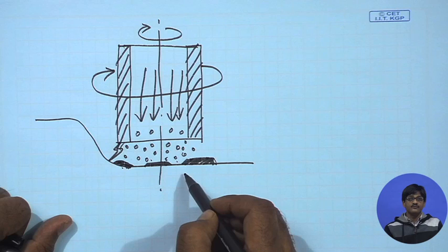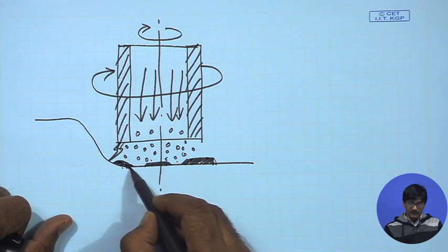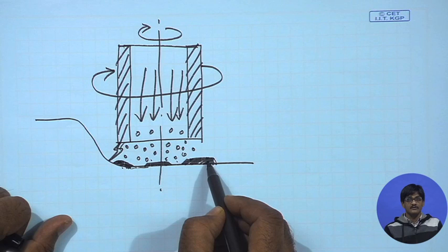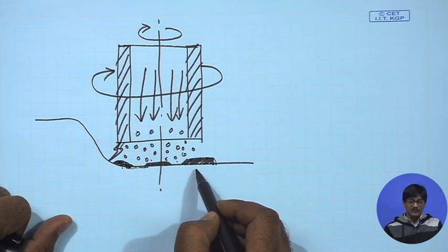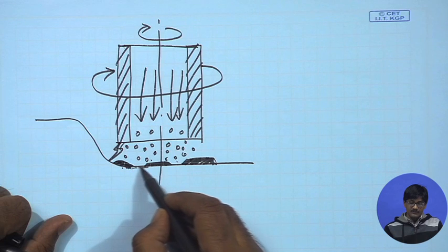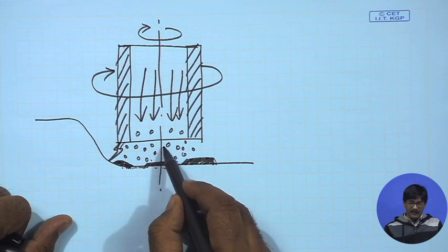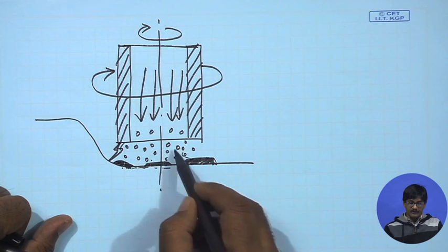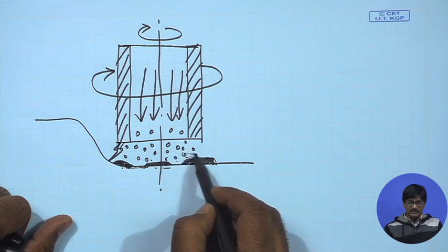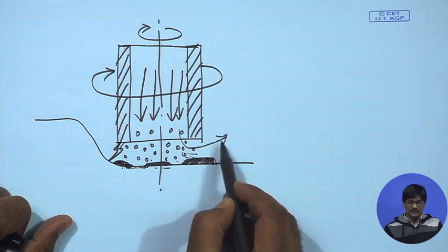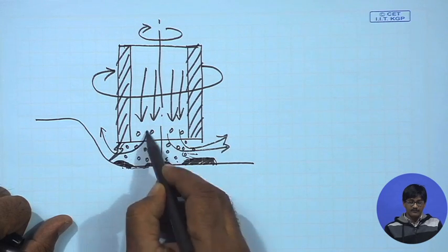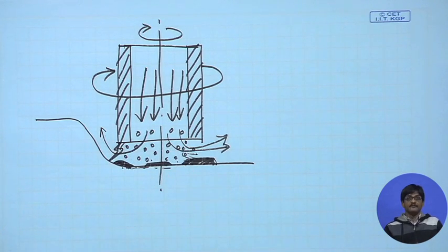The surface finish, which was obviously rough, because in some places you have recast layer and in some places you do not, and therefore the roughness would have been quite appreciably high, but once abrasives have acted on that, and all the metal debris which was sticking to the surface is driven off by the abrasives and the flushing action of the high pressure gas, we will find much better roughness will be obtained.